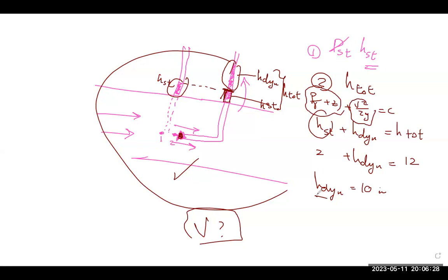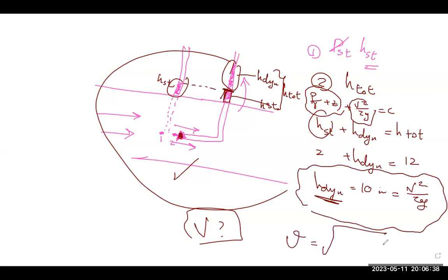So you have already deduced another equation for velocity, to get the velocity directly. So velocity will be equal to root of 2g times 10 inch. Finally, I need to substitute g. What is g? 9.8? No, this is British units, so root of 2 multiplied by 32.2, in feet per second square. And the 10 inch is divided by 12 to change it from inches to feet. This is one of the problems coming in the exam, with these same numbers. The same numbers? Yes, with these numbers.